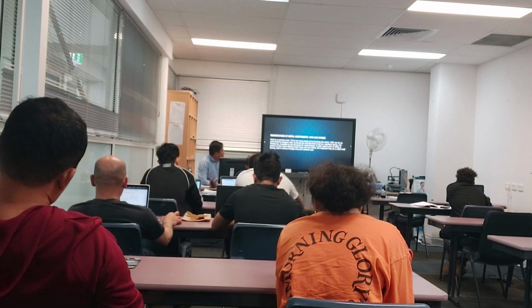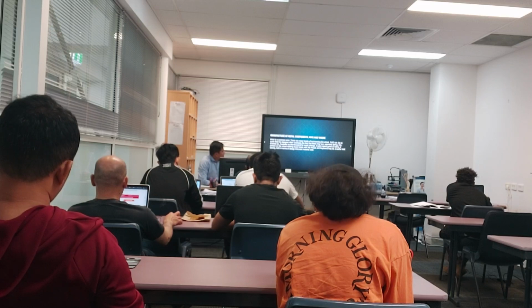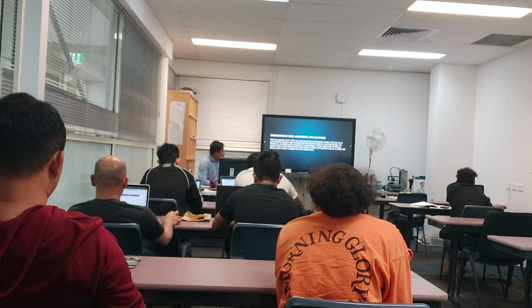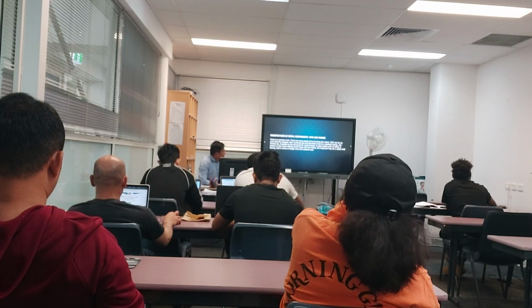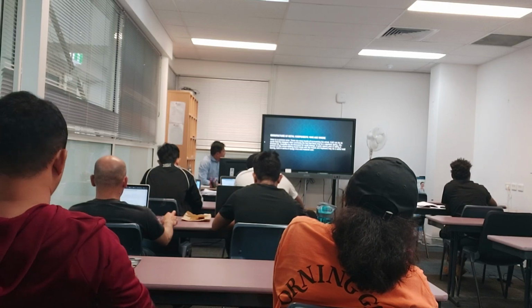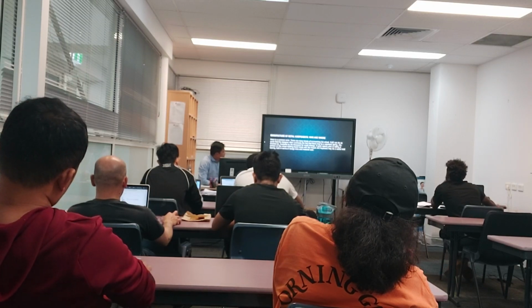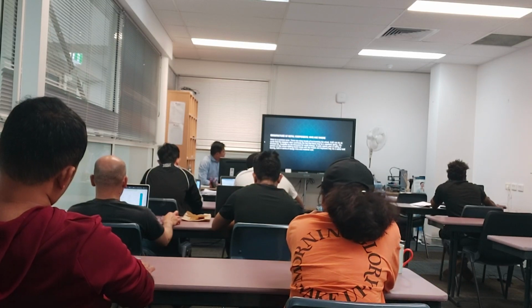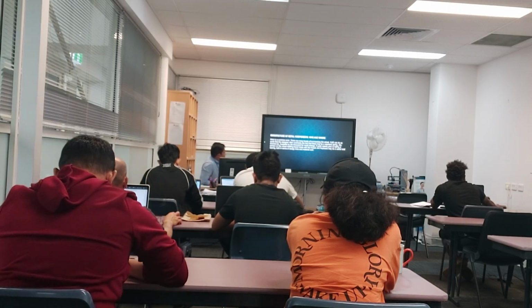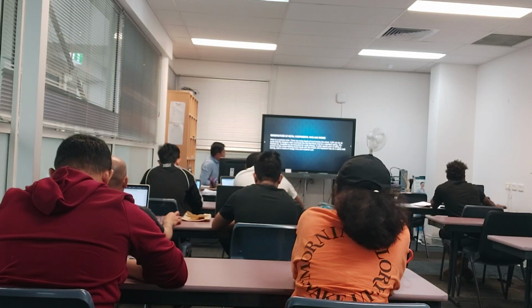So keep going. Manufacture of metal components, who and where. Here is a common error. There are many levels of reinventing the wheel. CAD can be so quick that the designer often overlooks the fact that there may be a standard spring, clip, bracket, etc. available by the thousand for small changes. A quick search prior to letting a person on the virtual drafting board loose with the mouse and keyboard may be a useful cost saving, both in terms of design time and material.